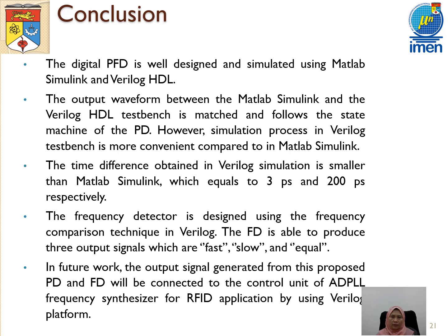And here we can calculate the time difference using MATLAB and Verilog as 200 picoseconds and 3 picoseconds respectively. And we also designed our frequency detector using a frequency comparison technique in Verilog, and this FD will produce 3 output signals of fast, slow and equal.